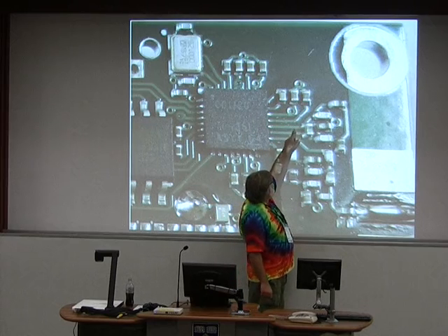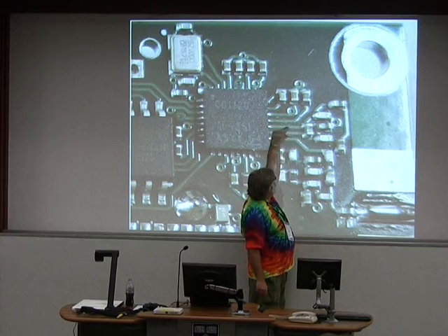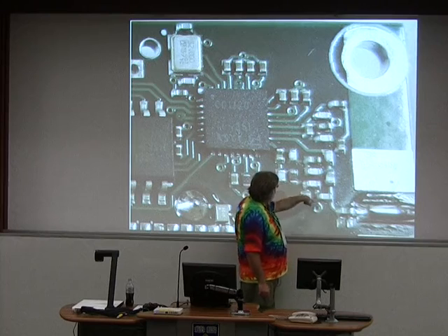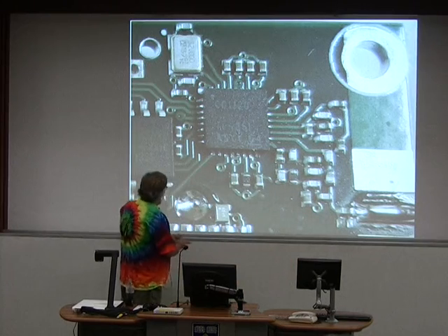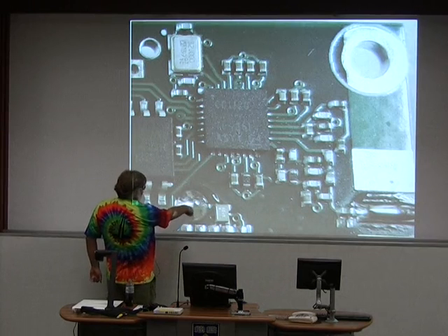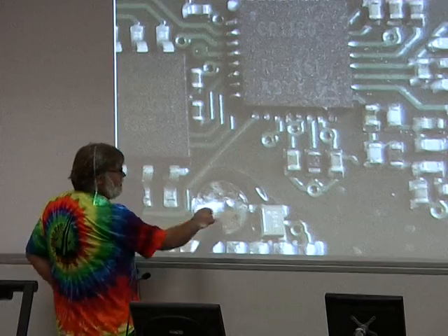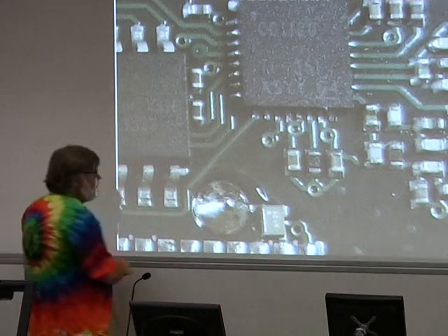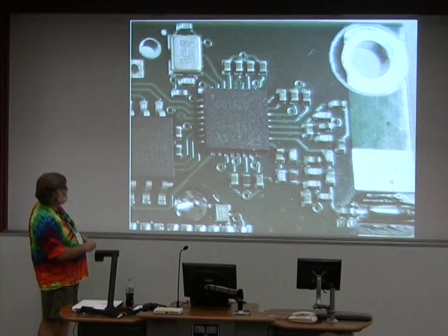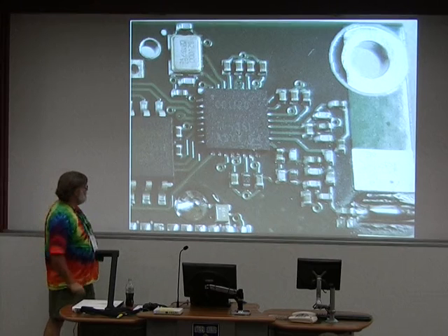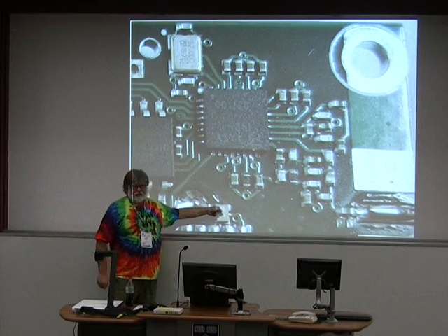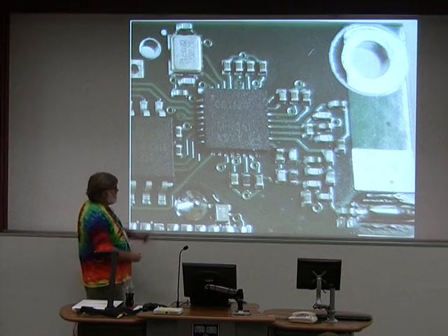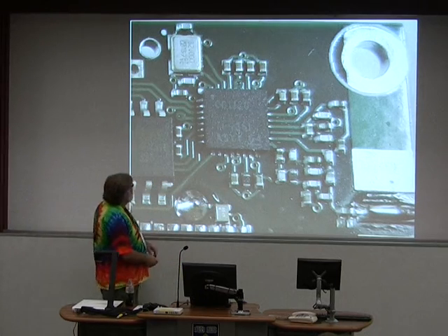You'll notice that in this case, the balun, I've got sort of nice trace uniformity out to here. It goes through the balun, and then this is all filtering down through here. Lots of bypass caps and all. This is where the GPS patch's pin is, and right there is 40 milliwatts of UHF. Distance-wise, that's that far apart. So that little part right there is the magic secret sauce. That little SAW filter makes all the difference. It allows that GPS receiver to not hear the UHF transmitter, and we get excellent GPS performance.